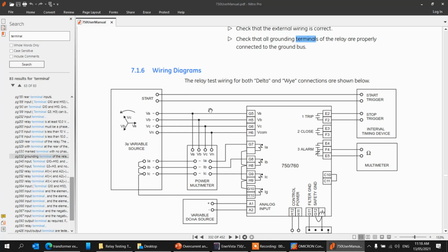If you don't remove F2, there's still a trip going somewhere, maybe an intertrip. That's why it's better to do dry, because you isolate that. If you leave that connected, of course the circuit is triggered. We don't know, it may trigger different signals.